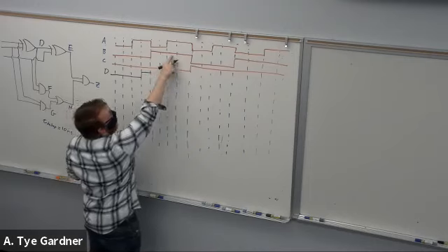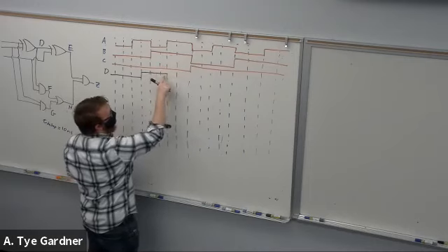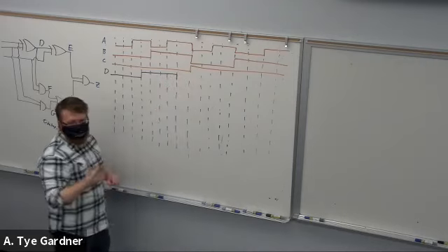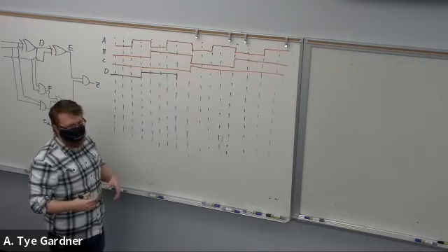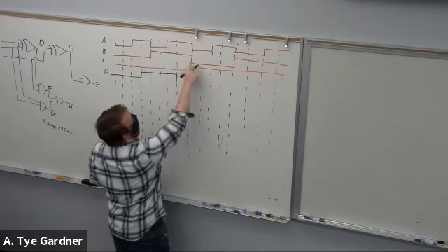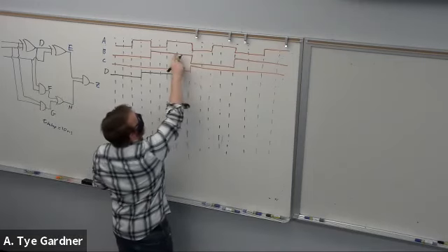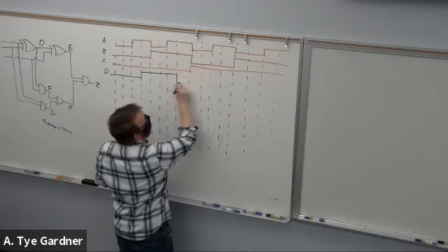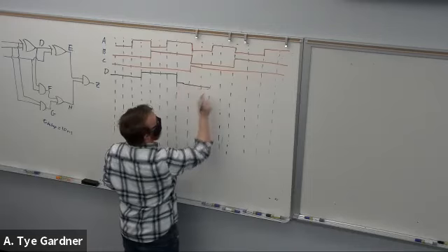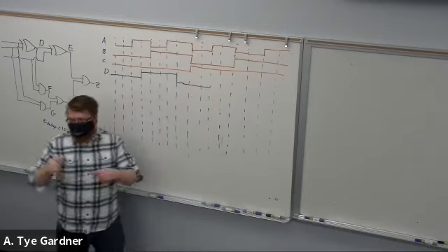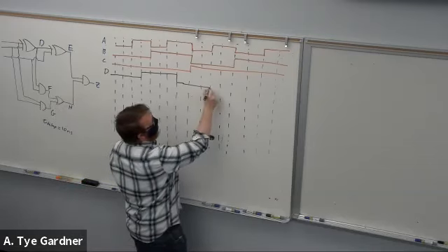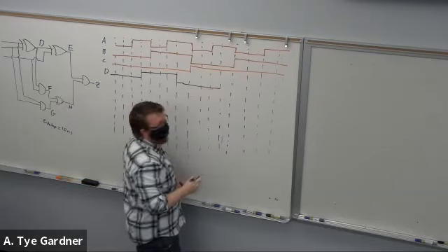Then they go back the same at this point, but it doesn't drop until a 10 nanosecond delay. So I'm just offsetting it by one set of bars. Let's keep going. They're back, so they're the same. The next time they become different is here. All I'm doing is seeing where the input's going to change, drawing it to that line, and then delaying by 10 nanoseconds.